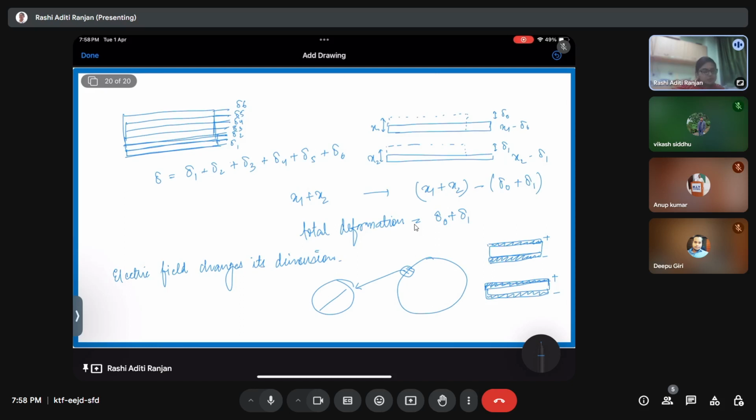This dielectric elastomer is also considered for vibration absorption because these materials, as you can see, change dimension, and they are essentially modeled through hyperelastic materials. You cannot compress it beyond a certain amount, and you can stretch it up to a certain amount only. So there is a kind of stiffness behavior, like it's a hardening kind of material.